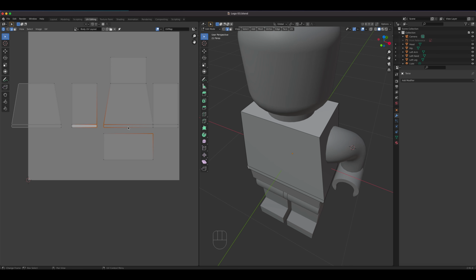So let's do the same thing. We can check that now. We can stitch that. All right, that looks like it's correct. I'm going to press enter. Then I'm going to select this edge. It's saying that it connects to that one, so this one needs to be flipped. I can select it like that as well, and on edge mode, I don't need to go to face mode. So S X along the x-axis -1.